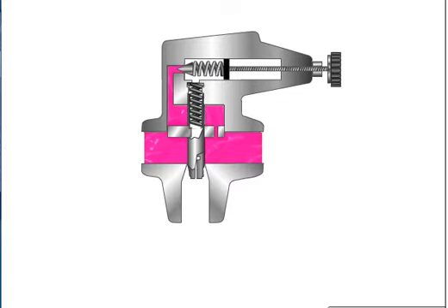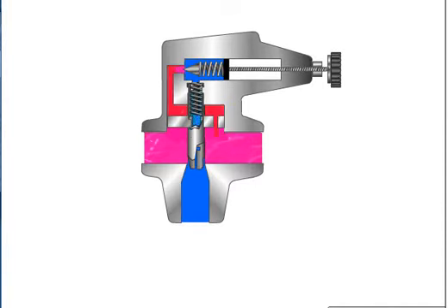When pump line pressure rises higher than the adjustment set on the control knob, the pilot relief poppet moves off its seat. This starts oil flow from the pump line through the orifice, across the pilot relief poppet, and to the tank. This restricted flow caused by the orifice creates a pressure difference between the pump line and the area across the pilot orifice. This pressure imbalance causes the main poppet to move off its seat. This will discharge enough of the pump flow to prevent any further rise in the pump line pressure.